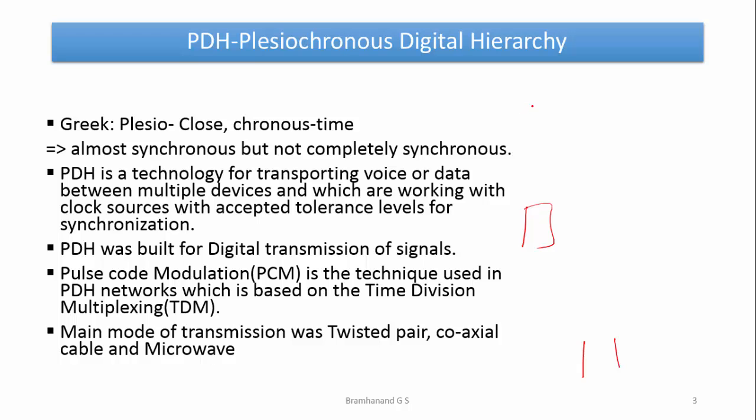As we discussed, the history of SDH SONET lies in PDH. PDH stands for Plesiochronous Digital Hierarchy. The word plesio means close, chronos means time. It means close time. It's a Greek word. It means almost synchronous but not completely synchronous. So PDH is a technology for transporting voice or data between multiple devices which are working with clock sources with accepted tolerance levels for synchronization.